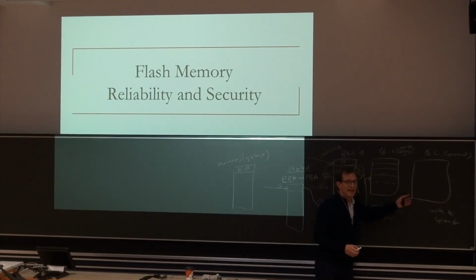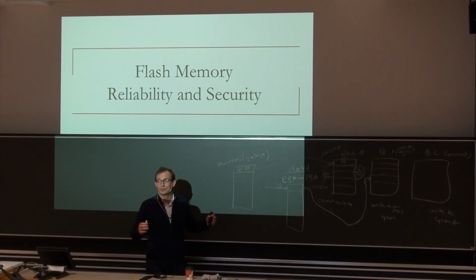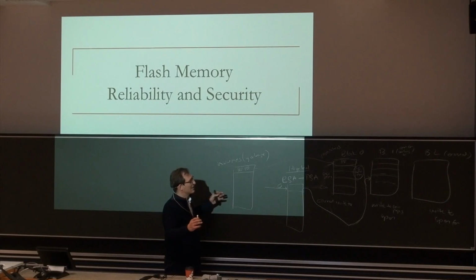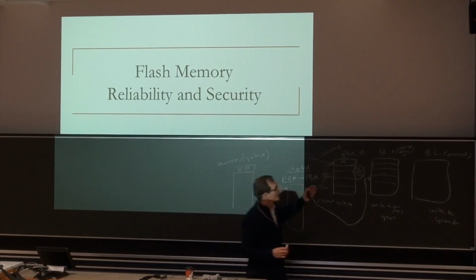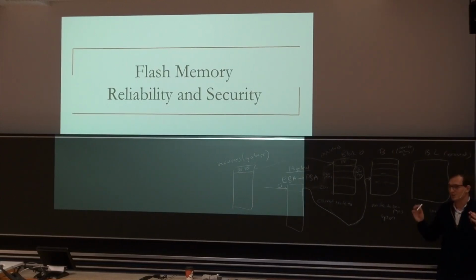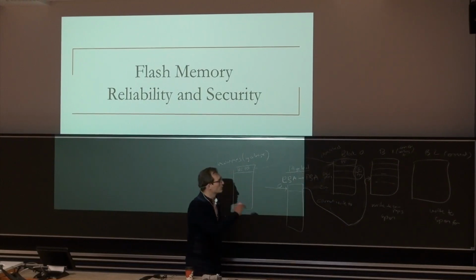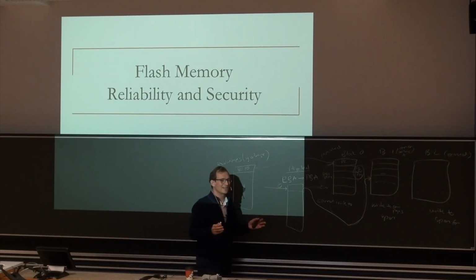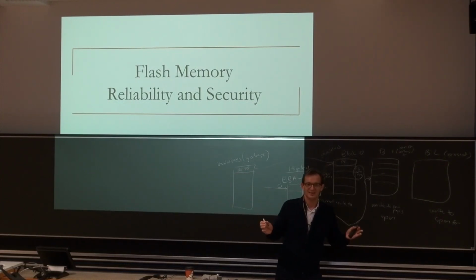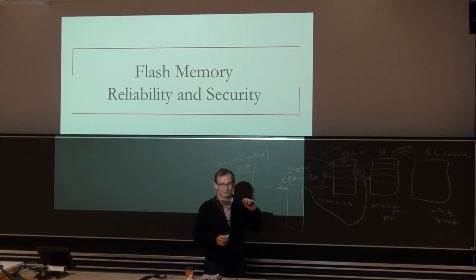And that is there because of technology constraints. So of course, to be able to do that, usually the space in flash drives is over-provisioned, meaning that they actually have more blocks than advertised to the customer, so that they can handle these sorts of moves more efficiently. Of course, over-provisioning is not good in general. Ideally, you don't want any over-provisioning because that costs, right? You would like to minimize the over-provisioning, but over-provisioning happens naturally because you want to handle these cases.